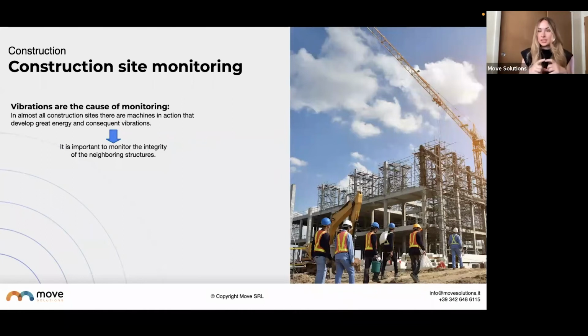We have a small sensor called the vibrometer. It's a PPV vibrometer, so it measures the peak particle velocity, which is basically just the ground vibrations that are caused from the construction that you're performing. So a great tool and something we're seeing a lot of construction companies doing right now is just adding these vibrometers onto their construction sites. They're very low cost. They're wireless, they're like this big, small sensor that you can put on surrounding structures so that you're not causing damage to them.